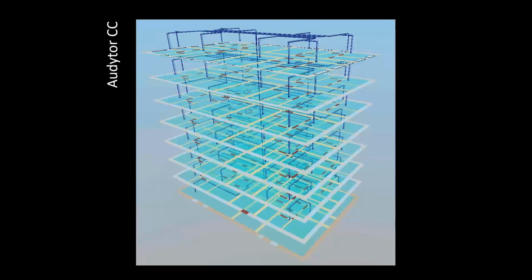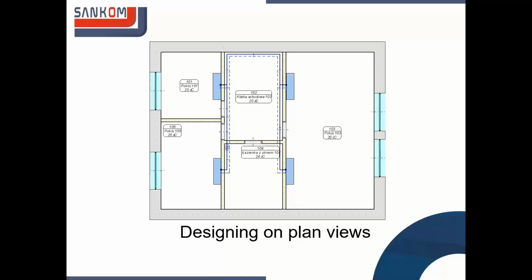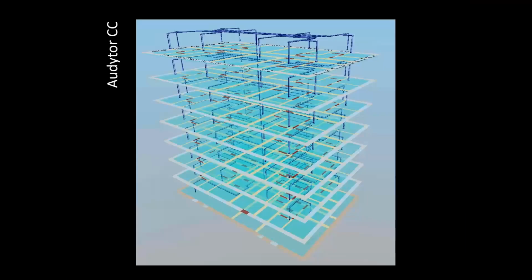And we developed the philosophy that it proves to be really effective because most of the time we don't work with the 3D. We draw the systems in the flat plan view, in the 2D plan view, and the third dimension is created automatically by the software using some information about the levels, and how these third dimensions are really very repeated.